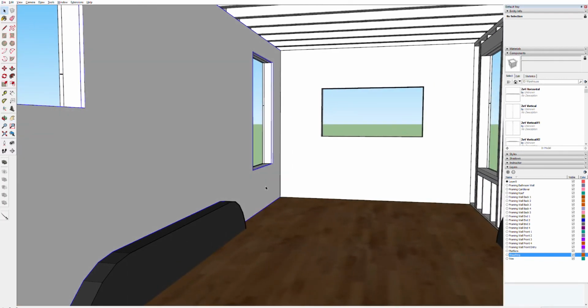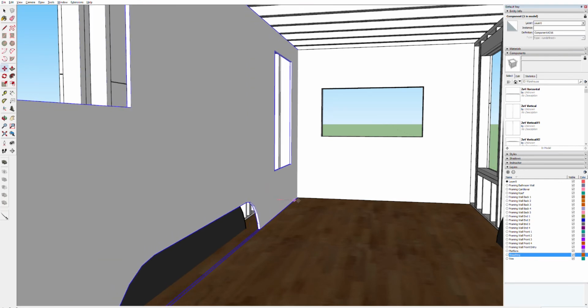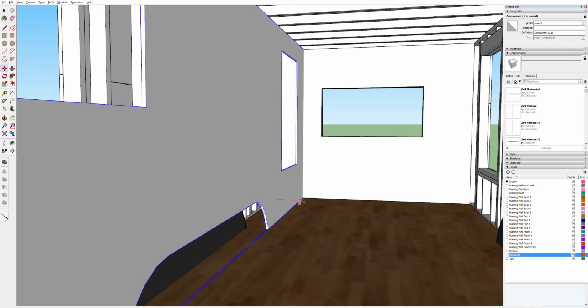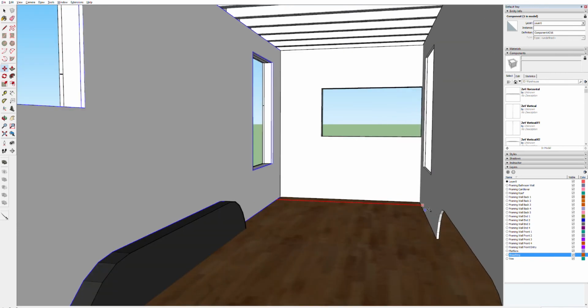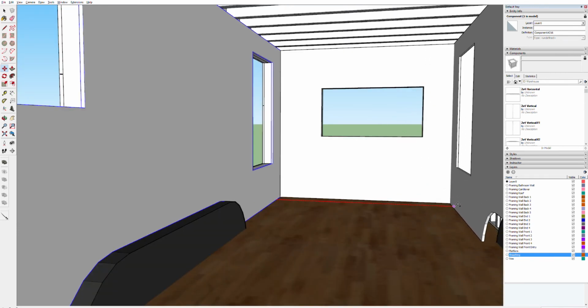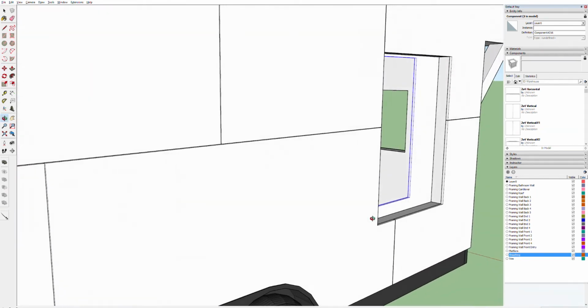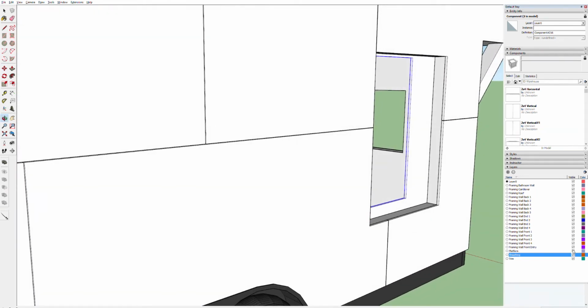Should have copied this wall over before I did that, but oh well. Okay, I'll have to seal up that framed opening now. Lock to red, copy, and let's rotate to outside, get rid of the sheathing.